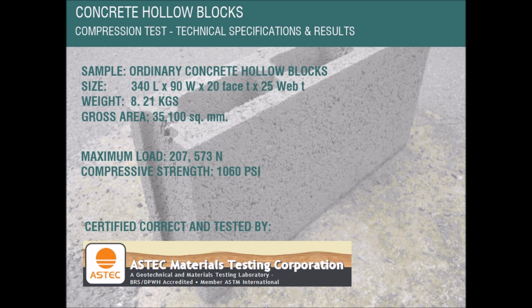Maximum imposed load of 207,573 newtons and compressive strength of 1060 pounds per square inch. This concludes that our sample is of normal weight capacity block.